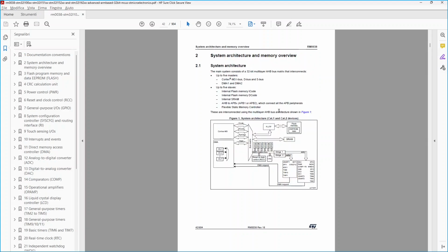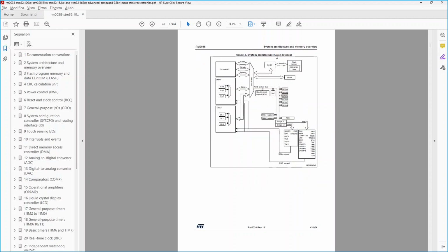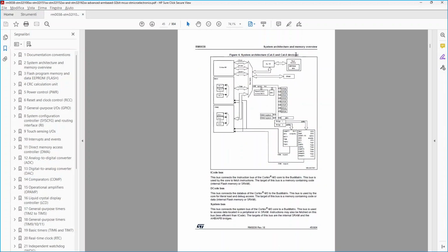Anyway, despite the category, we see that EEPROM is located in the flash memory area, and both flash and EEPROM are controlled by the same FLITF interface, managing read, program and erase operations on the non-volatile memory, the NVM device.